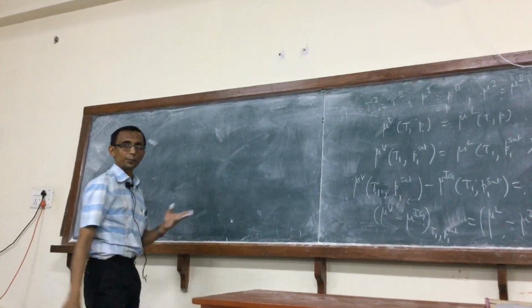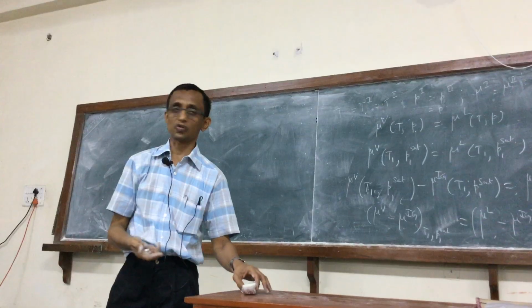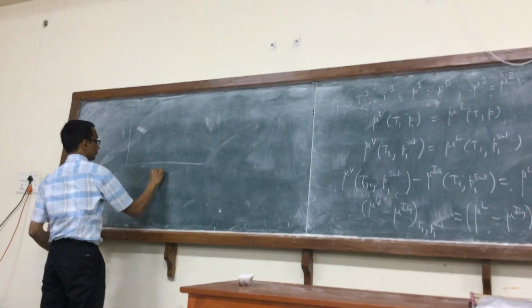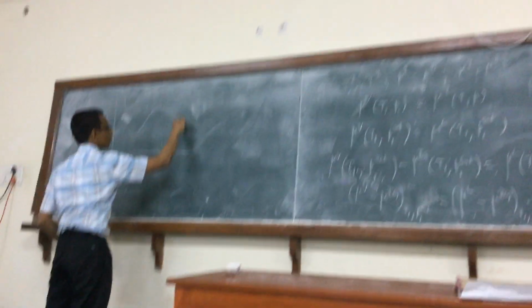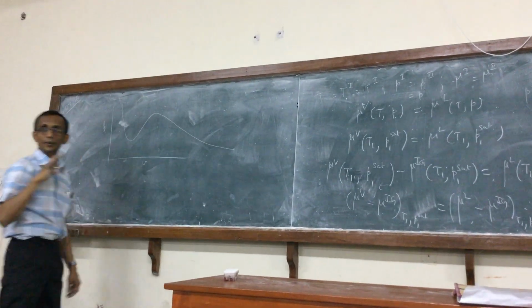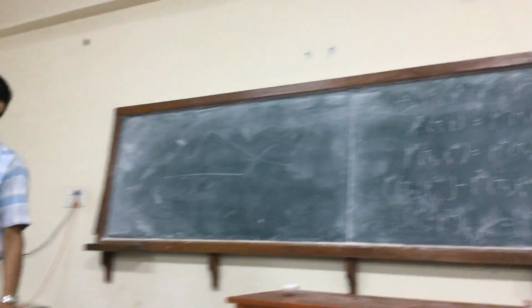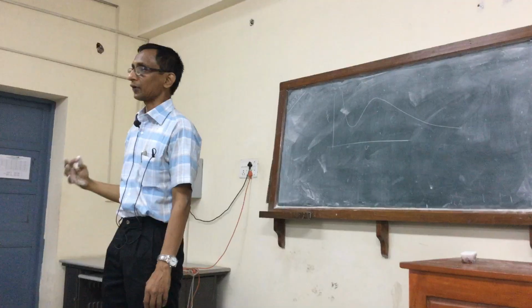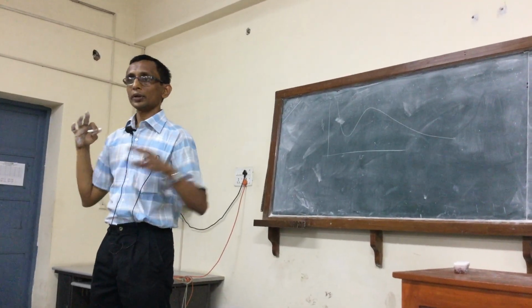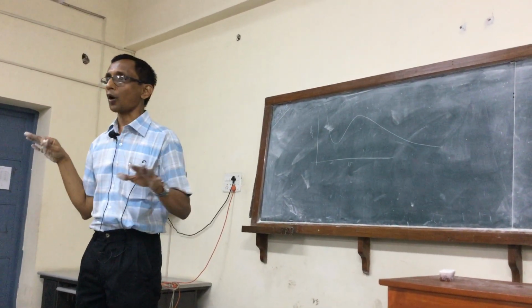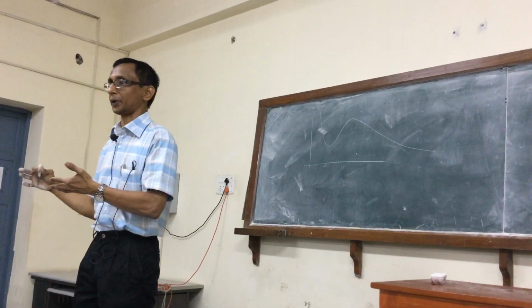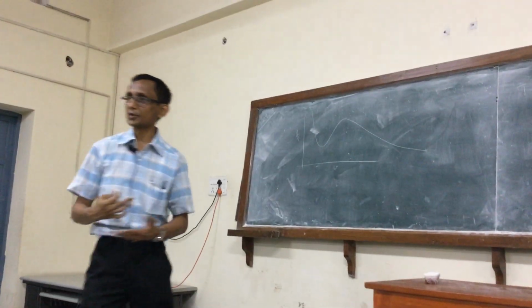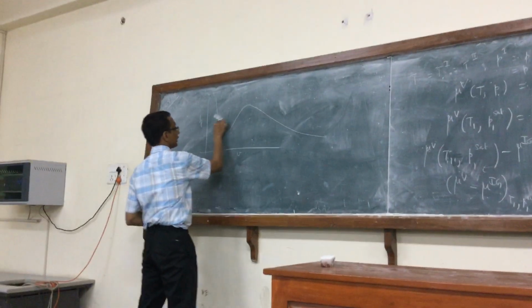Geometrically, we now see what the two terms in that equation mean. First I have the pressure volume isotherm. You take a look at the pressure at which the equation is satisfied. That's going to give me the saturation pressure as well as the liquid and vapor volumes. Once I know that the equation is satisfied, I automatically determine all three variables. The particular pressure is the correct pressure, and the calculated liquid and vapor volumes will be taken to be the saturated liquid and vapor volume.